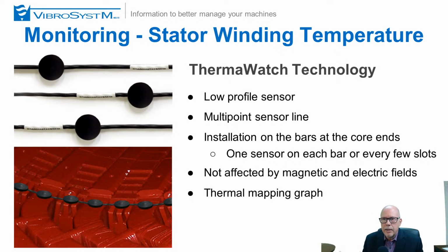Now, in regards to stator winding, we measure the vibration, as I indicated, which is very important, of course, but we also have equipment to monitor the temperature. We have a sensor that can be installed to measure the temperature of the windings coming out of the core. And as I mentioned in the first video, we also have a new sensor that's able to measure the velocity in 3 axes and also the temperature. So that might be an even more interesting product to invest in.